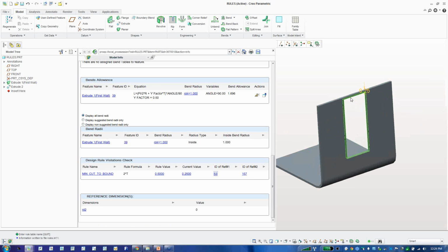Let's go ahead and modify that geometry. I'm just going to drag down. If I double-click on a feature, so that's another little tip there for you, and this actually is in modeling mode and in the Sheetmetal mode. One of the things I can do is if I double-click on a feature to edit it, which is the fastest way to jump into editing mode to get to the dimensions, it also throws me into auto regenerate.